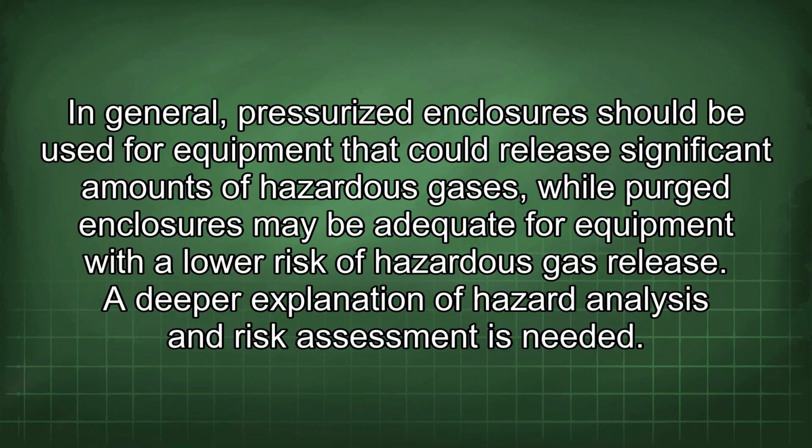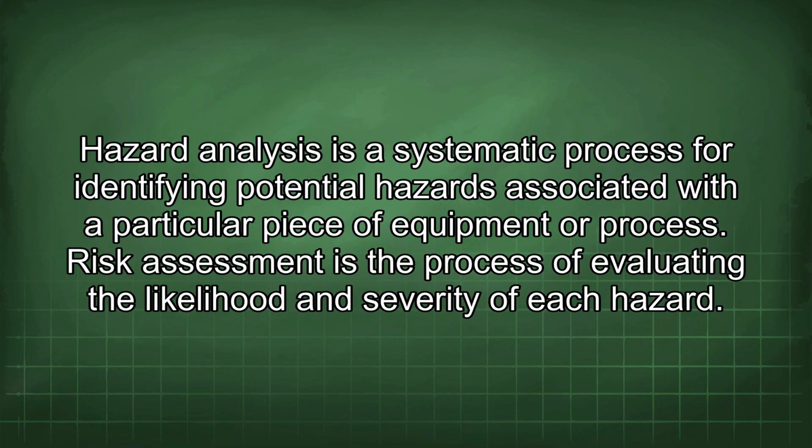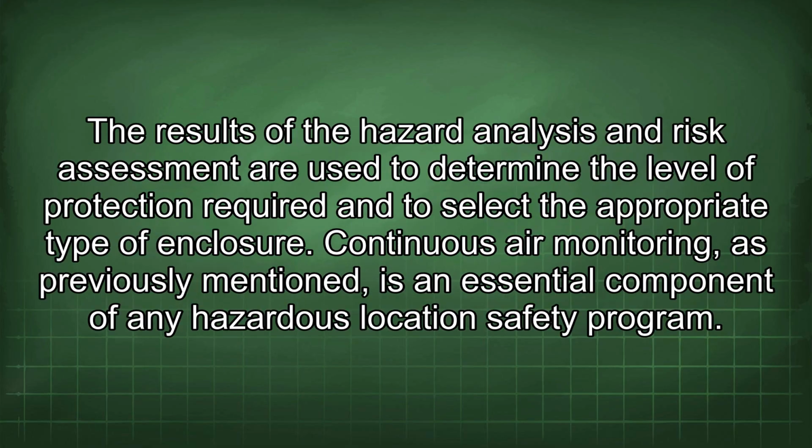A deeper explanation of hazard analysis and risk assessment is needed. Hazard analysis is a systematic process for identifying potential hazards associated with a particular piece of equipment or process. Risk assessment is the process of evaluating the likelihood and severity of each hazard. The results of the hazard analysis and risk assessment are used to determine the level of protection required and to select the appropriate type of enclosure.